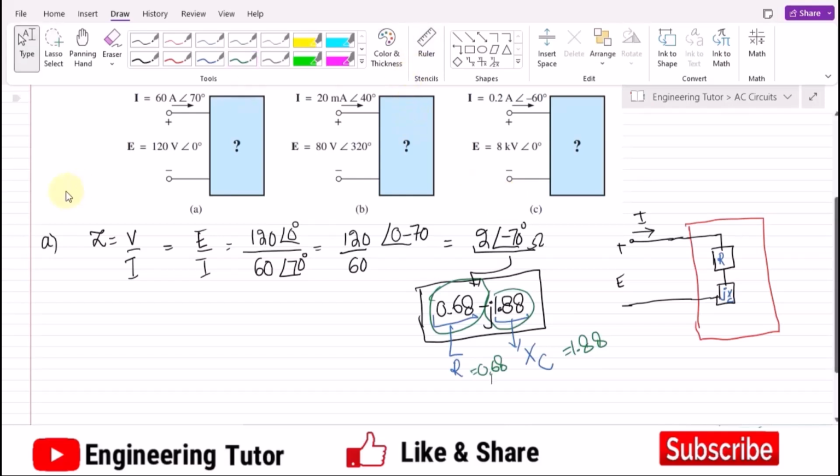Similarly, let me start part B of our question. Again the same scenario, the same formula is applied. Z is equal to V by I, where V is given, that is 80 volts at an angle of 320 degrees, and I is 20 milliamps, so 20 times 10 raised to power minus 3, and the angle associated with it is 40 degrees.